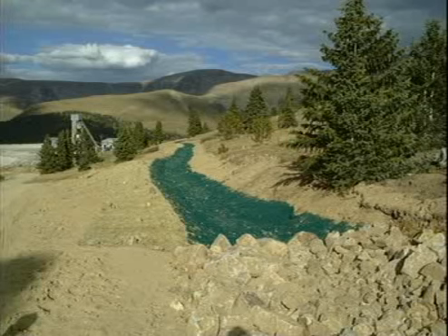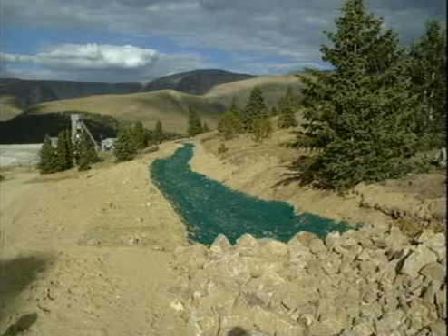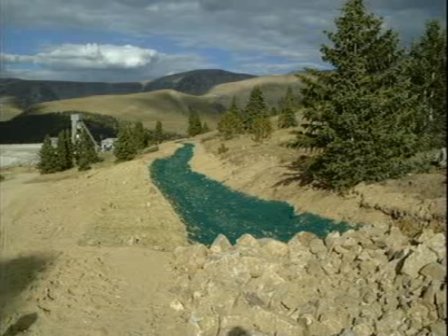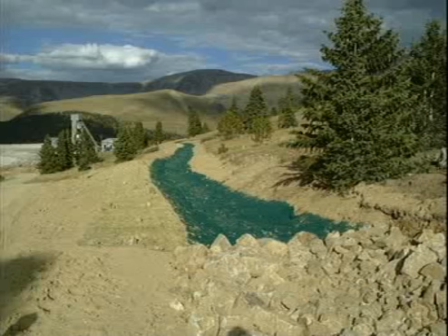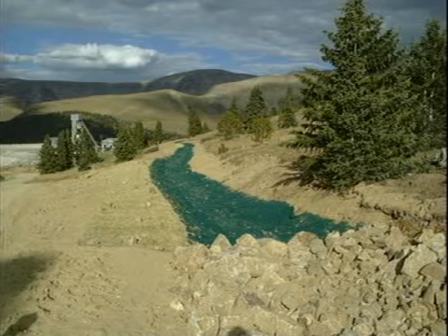That grass cover will help prevent erosion, just by capturing the water and allowing it to move on. The riprap liner is needed in streams where you have a high stream gradient, where the erosion potential is high. But the grass-lined ditch can be laid down where the gradient is lower and where the erosion potential is low. The grass-lined ditches are probably more for overland flow than down the ditch kind of flow. But the riprap ditches are really meant to work as a ditch to convey the water perpendicular to or at a steep gradient.